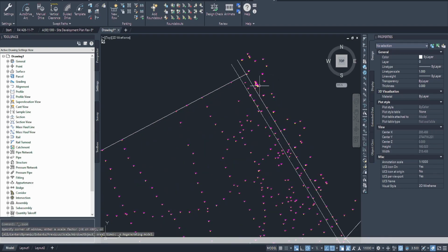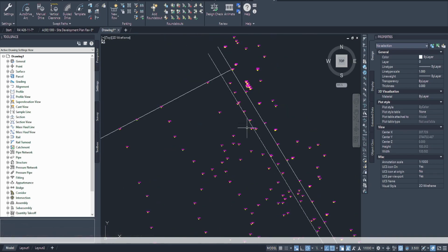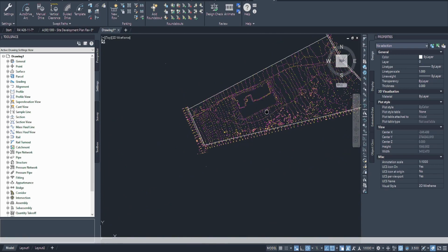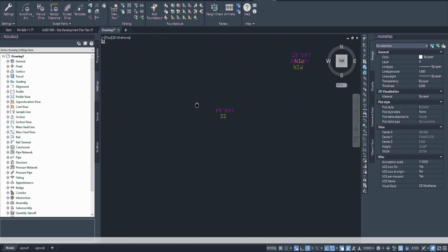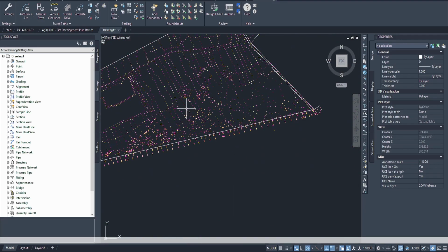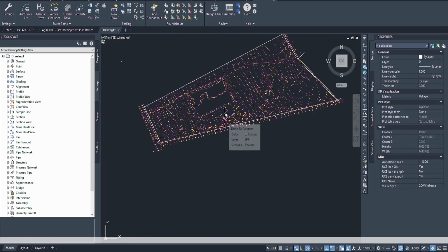Alright, once we focus on where the drawing is, these are the points we received. You'll see that this is the wrong way around, or upside down. This is because we work in the Southern Hemisphere, so everything should be a minus. There are various ways of dealing with this. You can turn your points, or translate and rotate the points to get them in the minus coordinates,